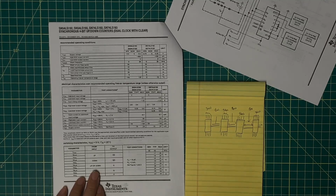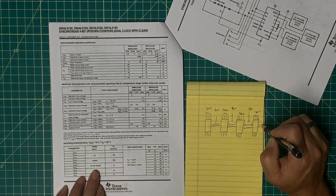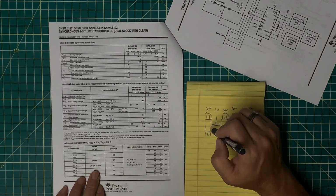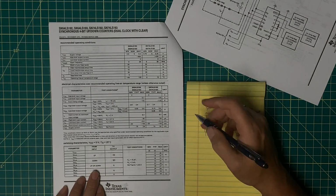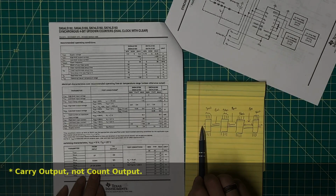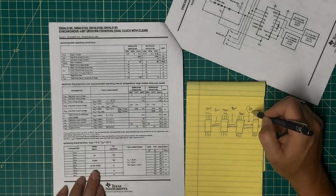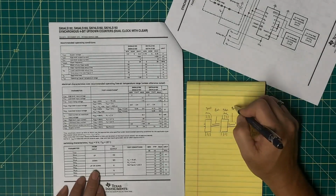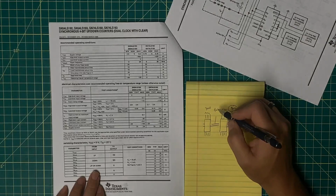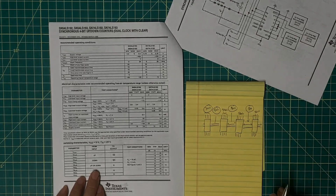All right, but what does that mean, Adam? Well, if I look at the longest path from the signal here to all the outputs stable over here, I'm frankly not worried about this count output or borrow output on this most significant. I'm not doing anything with that. So my high water mark becomes this 18 nanoseconds, this 18 nanoseconds, this 18 nanoseconds, plus this 30 nanoseconds.